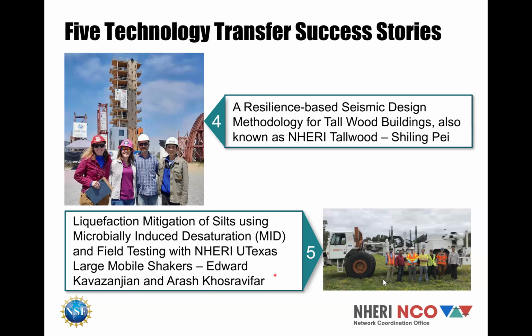And then another one was 2 researchers, Edward and Arash, working on mitigating microbial-induced desaturation. So soils liquefy only if they are saturated. And so this is a new approach, MID, to reducing and maintaining a low level of saturation in soils that would otherwise liquefy. And with the help of the T-Rex, this is the big one, from University of Texas, and Ken Stokoe, the PI, they were able to prove that that works. And that now is, once they've published, geotechs can now use that as a remediation of liquefiable terrain. A very useful discovery. So those are success stories.